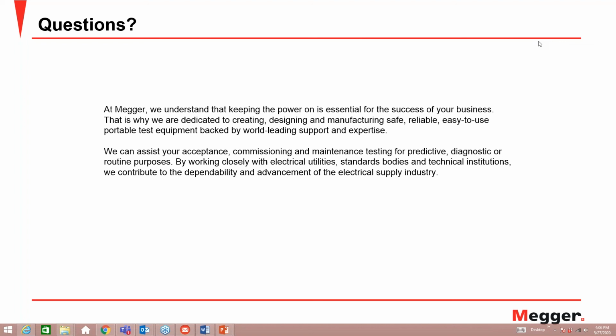I can add to that. Typical values which are seen for vented lead acid is 7% of capacity. NiCad is 20%. Sealed lead acid is 10%. But as Andy said, it's best to contact the manufacturer. But these are the typical values that are seen for different battery types.